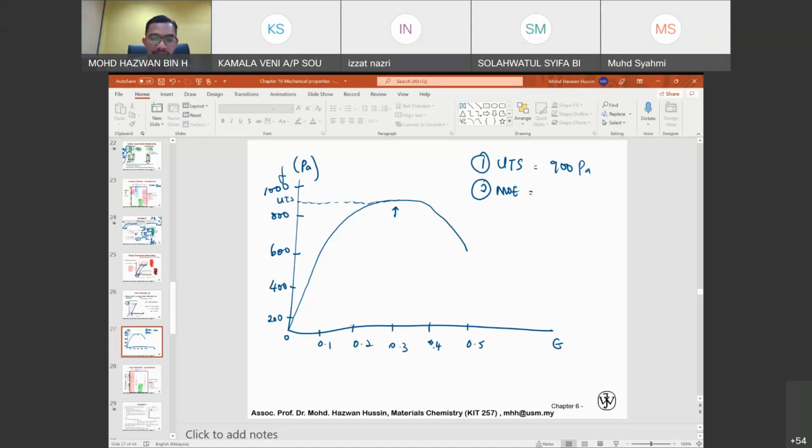So when we want to find the slope, before you calculate it, you have to make sure which part is actually the linear region. So the most important thing is to note that. Like for example here, we know that this is the elastic deformation region, and beyond this it starts to bend, and this is where plastic deformation occurs.